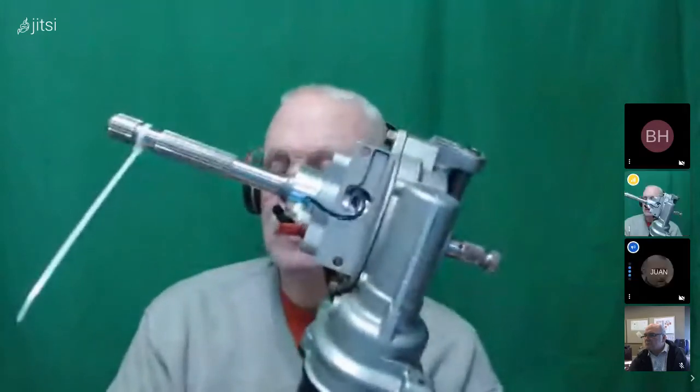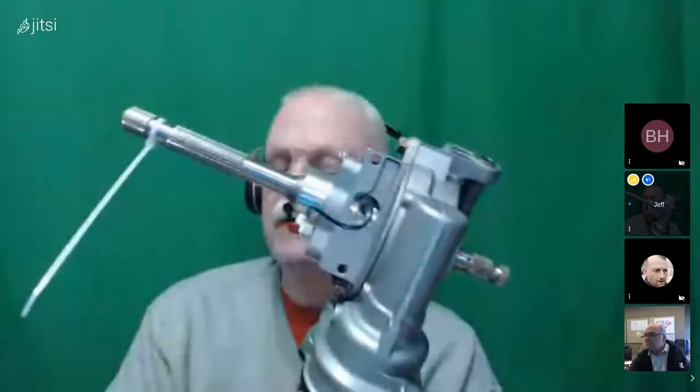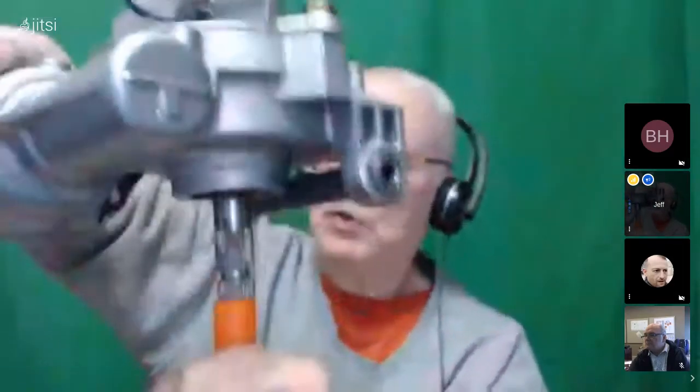I was asking that. Thank you. So what I'm going to do, if I bolt this straight onto the shaft like this, boy, that motor's heavy. If it's straight on the shaft like that, then I think what you did was, on the top of the shaft, you put a potentiometer in here with a little bracket to hold it. So that's how I can measure my feedback, by using a potentiometer or one of those little Hall effect things that looks like a potentiometer.